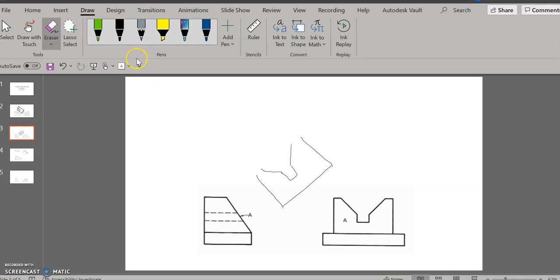I don't need it. I'm going to go back and re-add in my top surface here and here so that is complete. Now I'm also going to have to draw the other edges that I do see, so I'm going to project that back. I'm going to draw a projection line, and this projection line has to be 90 degrees from the surface in question. Same here, and then also same here.